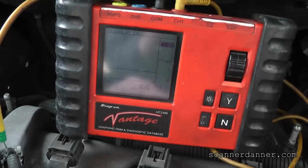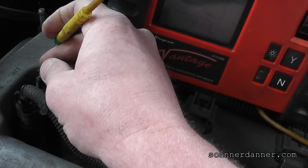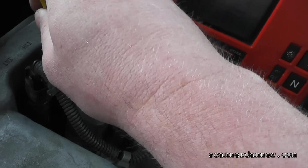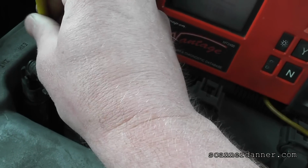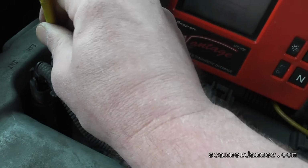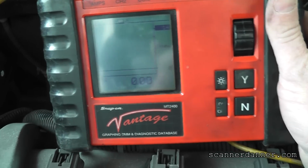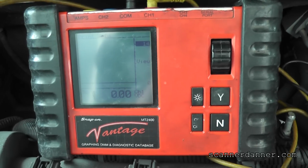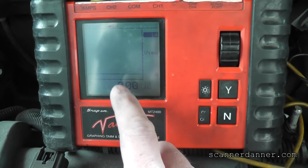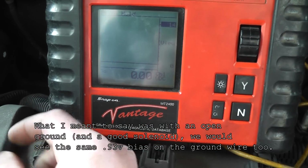See, I don't like that 2.44. I'm not sure of the computer logic there. That wasn't there a minute ago until I started these bi-directional tests. This isn't changing the fact that I need a solenoid, guys. I'm just trying to figure out the controls here. Working on something new. See, my ground is good and steady. So no question the ground is good here. If you think about this, if the ground was open, that would act as an open solenoid, and we would have seen that 0.9 of a volt on the control wire with an open ground. I'm not worried about an open ground here.